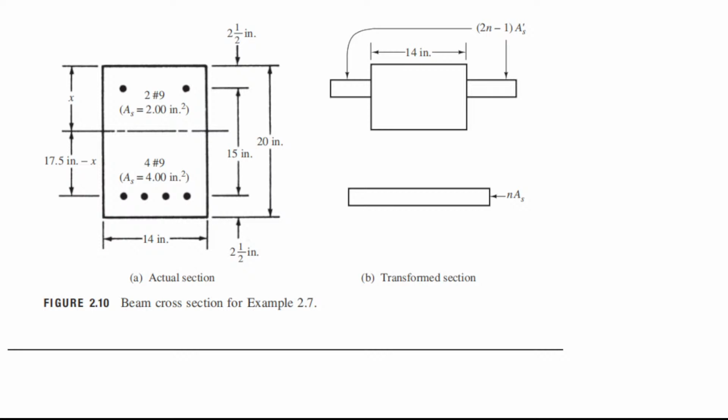Another is that it is the minimum concrete cover so that we have the optimum bonding between the two materials. That is another explanation why we need concrete cover. So there are at least three reasons for that.